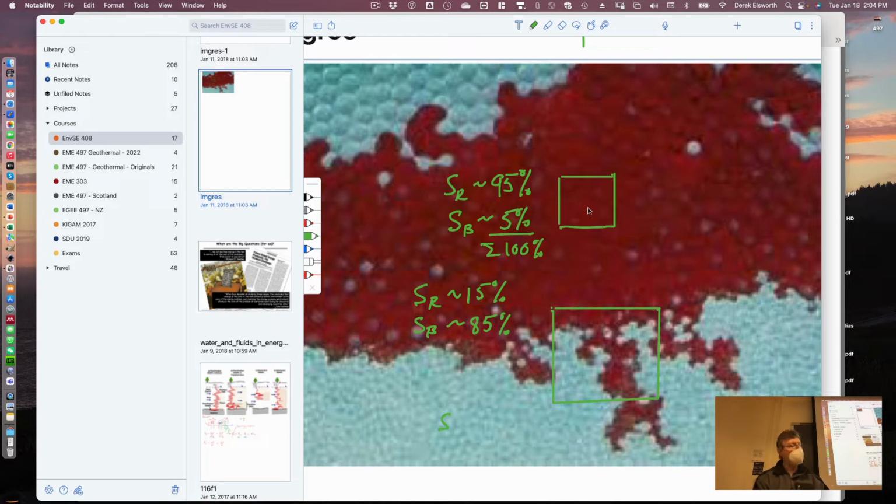But what's going on here? Well, we said last time about the relative saturations that the water would coat the particles, and it would have what we called pendular saturation. So where one particle joins onto another, there's a ring around it, a donut or a torus, which is the covering of the particles in water, but also a bit more water at the edge. And so clearly within here, it doesn't really look like our capillary tube, but it has the same kind of behavior.